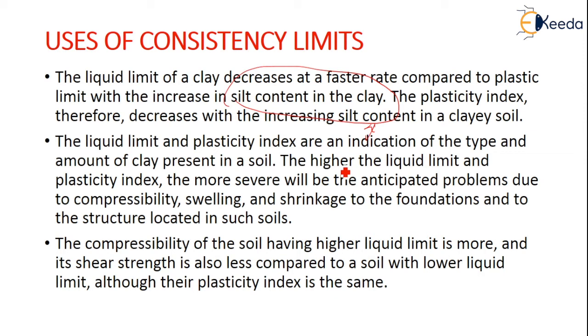Again, the liquid limit and the plasticity index are an indication of the type and the amount of clay present in the soil. Like, they tell us the amount of clay which is present in the soil. The higher the liquid limit and the plasticity index, the more severe will be the anticipated compressibility problems like swelling and shrinkage to the foundations, and there may be differential settlements to the structure located in such soils.